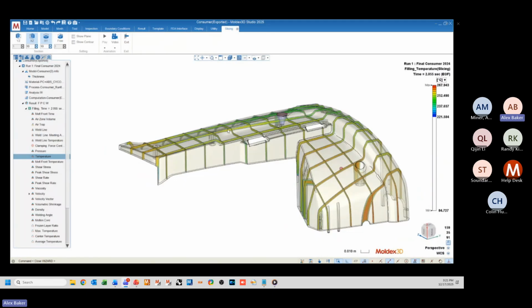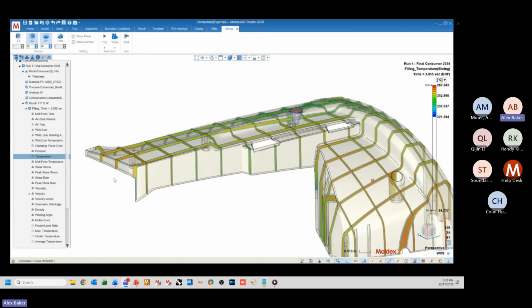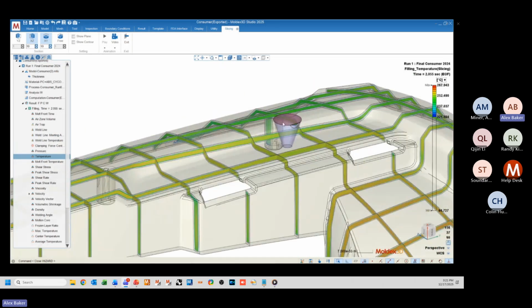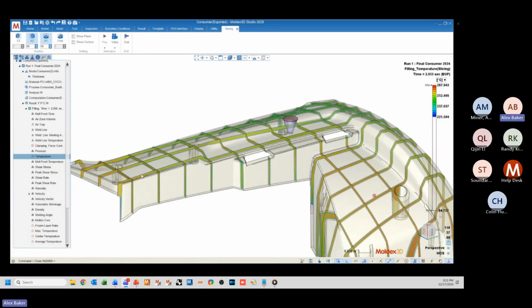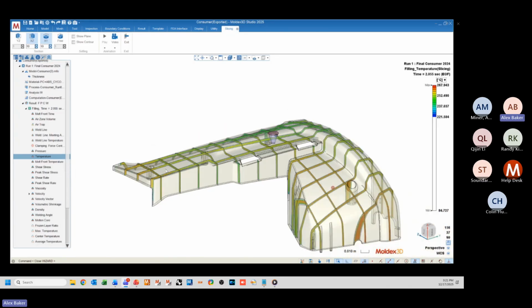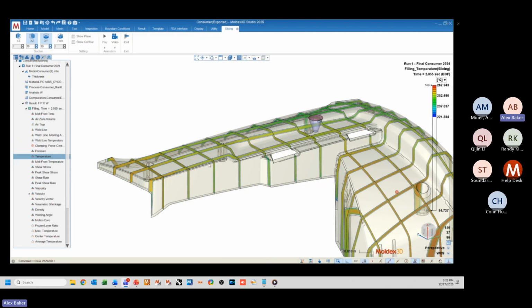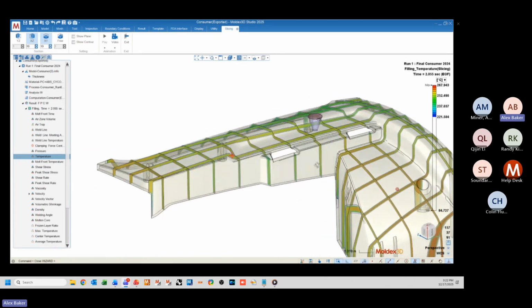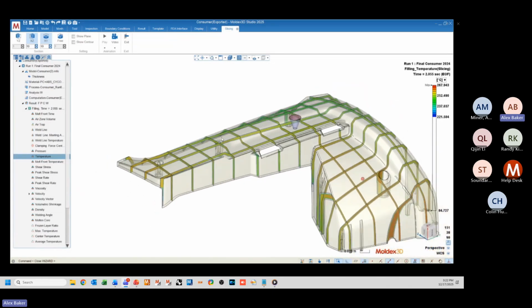And actually, in this case, we can see that the temperature at the end of fill is higher than the gate location, which is kind of counterintuitive. You would think that the heating source is at the melt entrance and that heat, that energy, should be releasing out into the mold as the material flows, which means that the material's temperature should decrease over the length of fill. But actually, the shear heating effect in this case caused the temperature to increase over the length of fill, which is likely a proponent of the filling speed that we elected to use in our process.